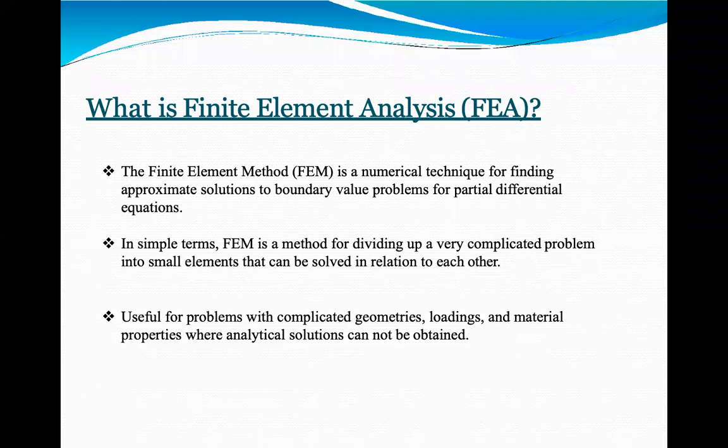Now, when should we use the finite element method? For simple problems, like if you want to analyze a simple bar or beam or shaft, you can simply do it with your strength of materials and design of machinery element knowledge. You don't need the finite element method for simple problems.